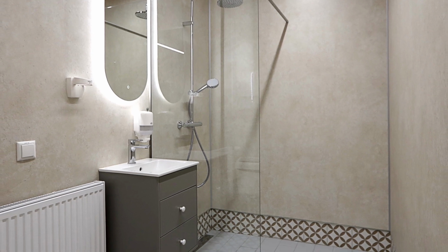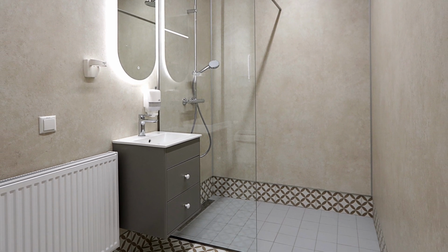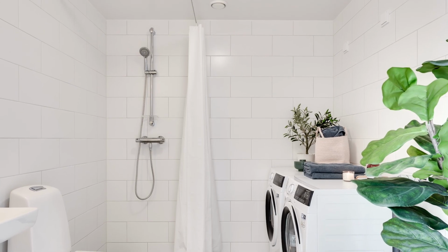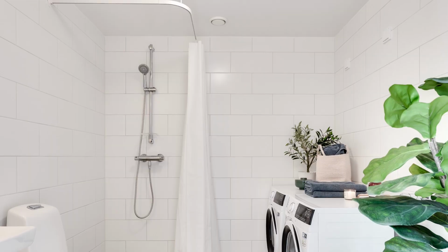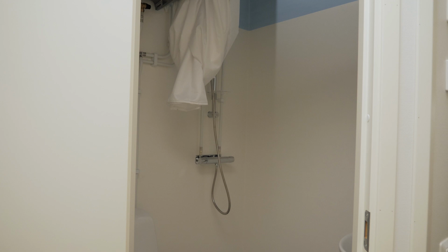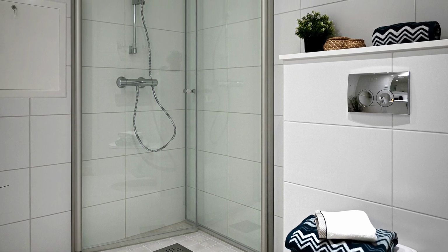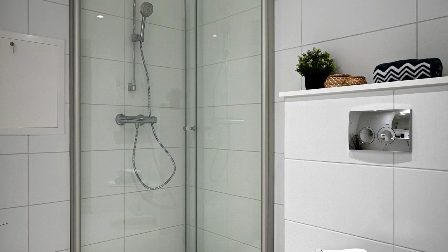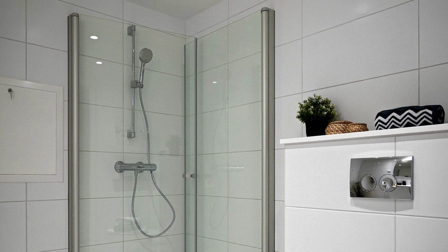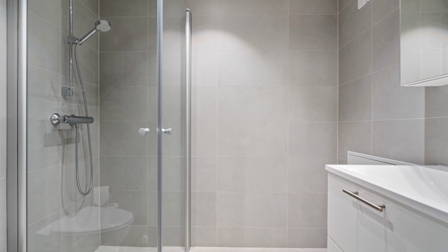That can be achieved either with a strong moisture-resistant fabric or, quite often, a mastic with specific thickness is applied on the surface. Ceramic tiles are usually installed on top of the waterproofed surface. Sometimes wall or floor covering vinyl is used. In this case, no additional waterproofing is needed. It's important to note that a ceramic tile wall covering is not a vapor barrier and doesn't provide a waterproof layer because its joints may contain microcracks and allow vapor and water to penetrate, so waterproofing is always necessary beneath the tiles.